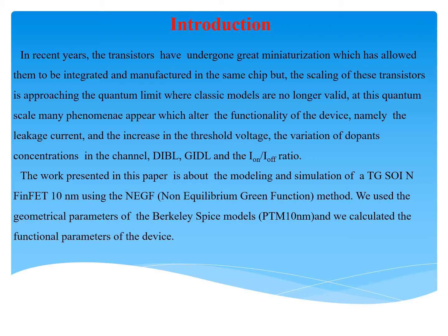Introduction. In recent years, the transistors have undergone great miniaturization, which has allowed them to be integrated and manufactured in the same shape. But the scaling of the transistor is approaching the quantum limit, where the classical models are no longer valid. At this quantum scale, many phenomena appear which alter the functionality of the device, namely the leakage current and the increase in threshold voltage, the variation of dopants concentration in the channel, DIBL, and the Ion per Ioff ratio. The work presented in this paper is about the modeling and simulation of Tri-Gate SOI FinFET 10 nanometer